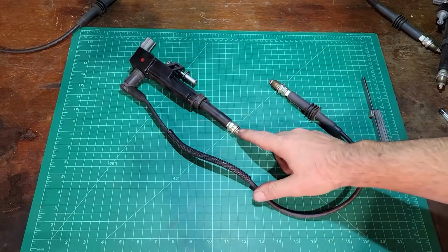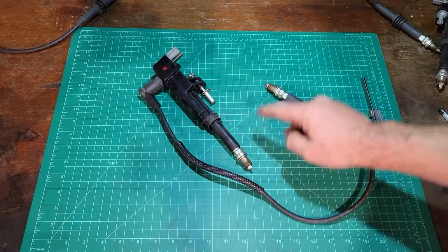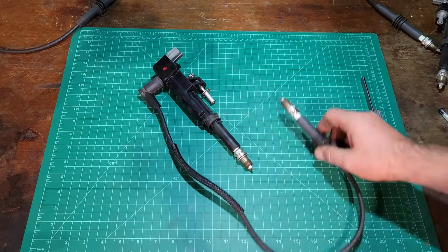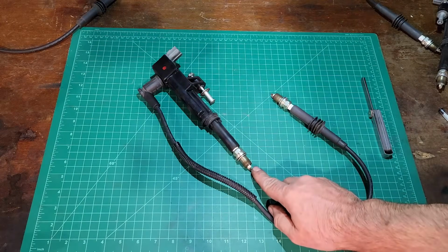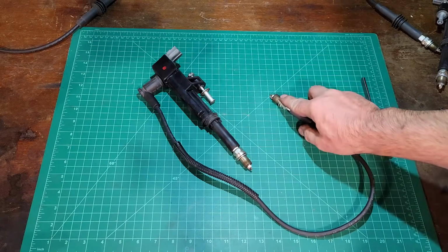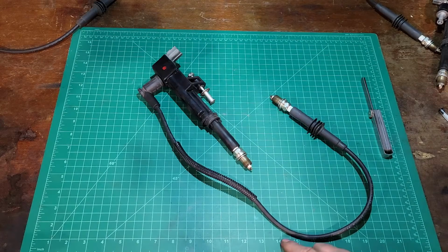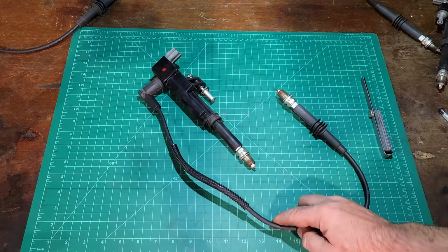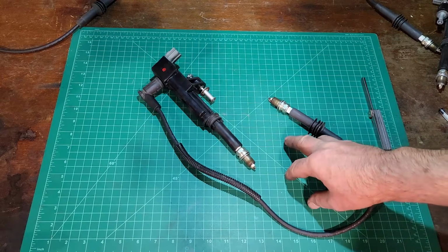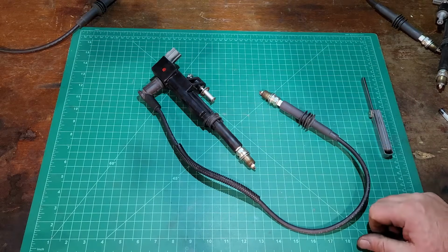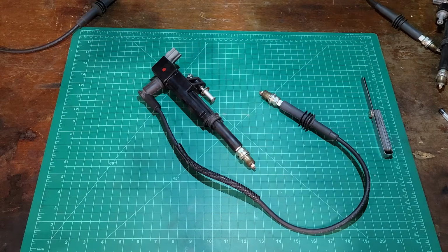All right, guys, the first contender, we have coil number 1 and cylinder number 4. That's what it controls. It's a waste spark system, so it's just basically getting back home. This plug gap was at 58 thousandths. This plug gap was at 38 thousandths. 43 is what we're after. The plug wire was at 11,750 ohms. The spec is 10,000 or below is good, above is bad. So this wire is technically on the bad side. Not enough to cause the computer to take 10% of the fuel away, but it's slightly out of spec.